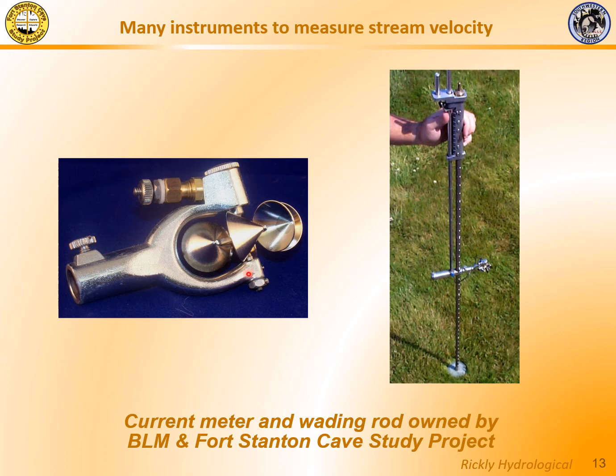The device on the left here is a current meter. It is a vertical axis current meter. There is a bucket wheel mounted on a vertical axis here. It's very similar to an anemometer you would see at a weather station used to measure wind velocity. The bucket wheel is designed to work underwater, and the bucket wheel spins faster as the velocity increases, and a device that counts the revolutions, calculates the velocity, is attached to the bucket wheel.